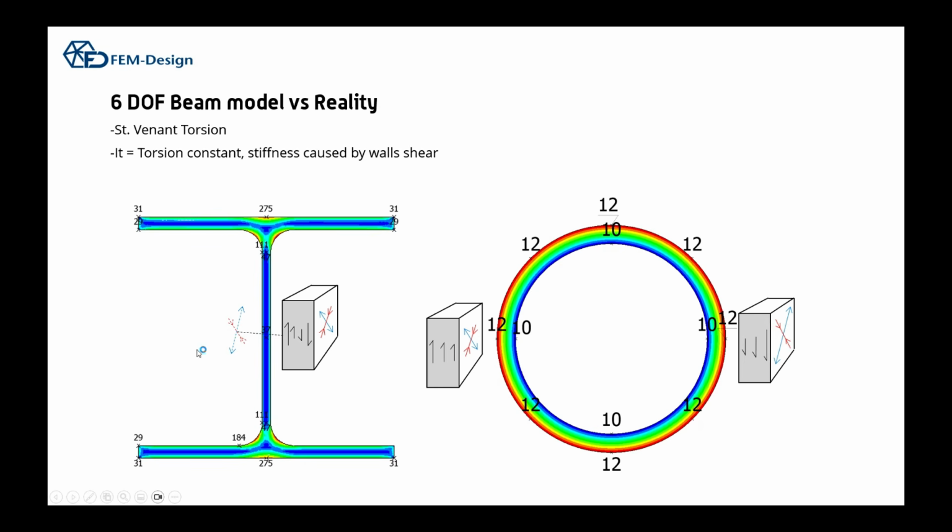This will come in handy if you think of this as two principal stresses when you think about shell models and how warping or St. Venant torsion works in shell models. It's easily described as shear related, so it's just proportional to the shear modulus, the torsional stiffness of the cross section and the angle of twist. So it's really simple to describe with this equation.